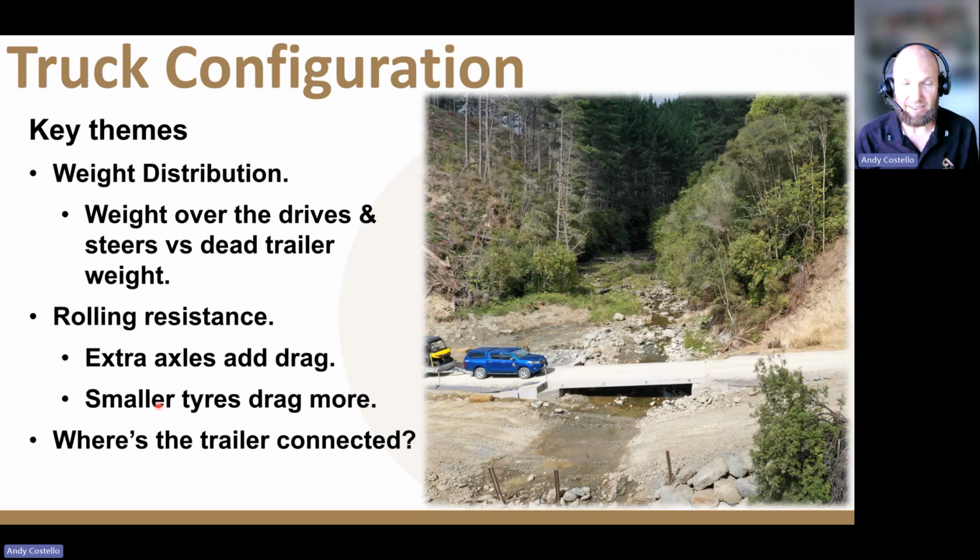The key factors that impact what we can do in terms of maximum grades are the weight distribution, so specifically how much good weight you have on the truck, increasing the traction on your drives and your steers, versus the bad weight on the trailer, which is fighting you as you're trying to drag it up the hill and trying to pull you offline as you're trying to get round a corner. Also, the number of axles has a big impact. Every extra axle is more rolling resistance.